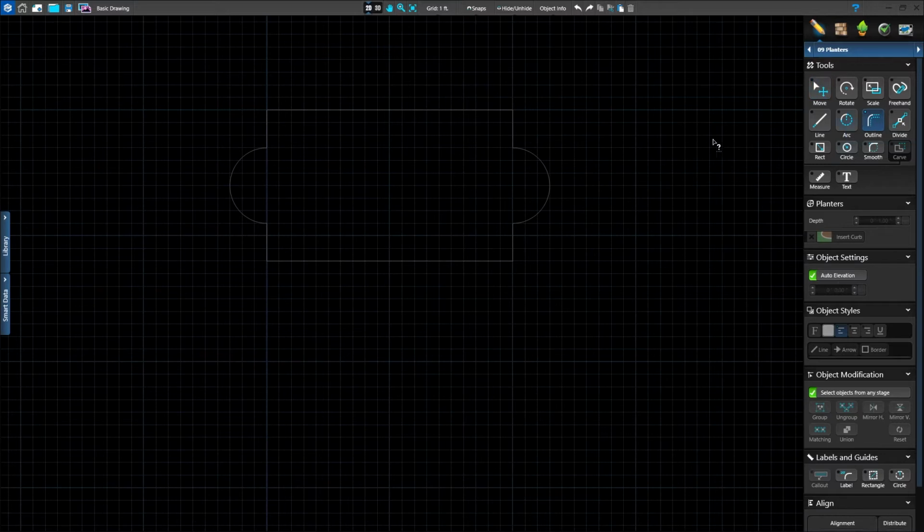When the cursor enters the 2D grid, the cursor has a question mark. This indicates that an existing shape needs to be chosen. Step 1 is to click on the shape you'd like to outline. So we'll click on the hardscape.